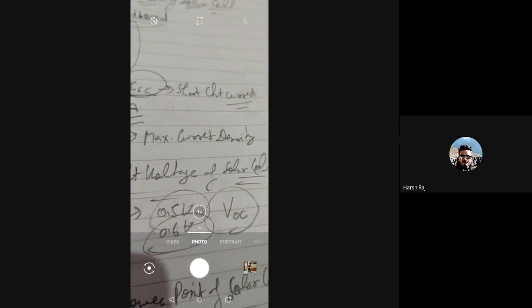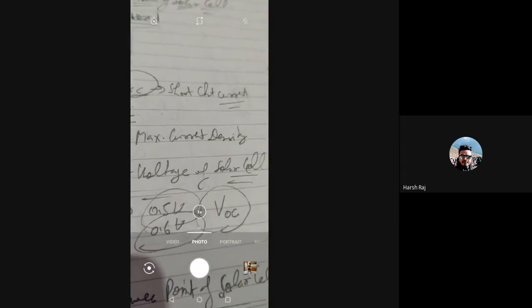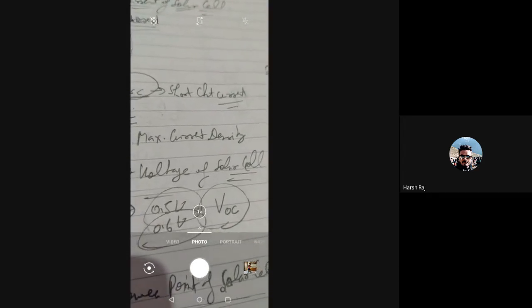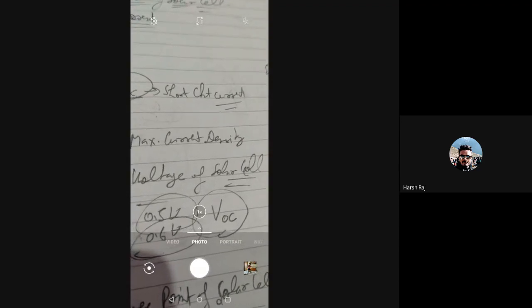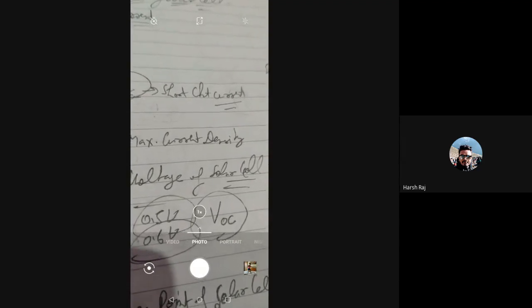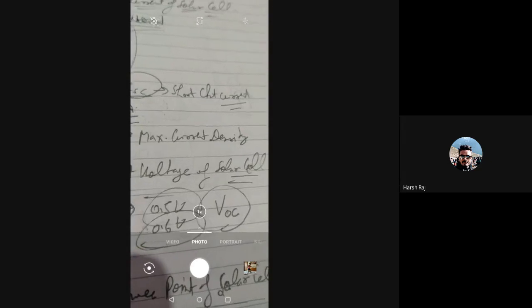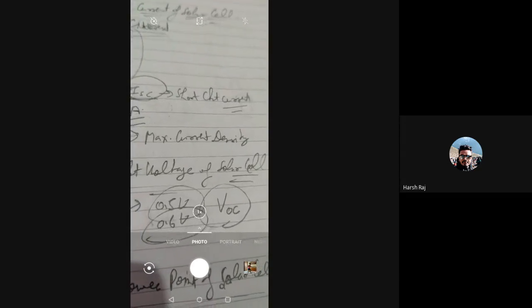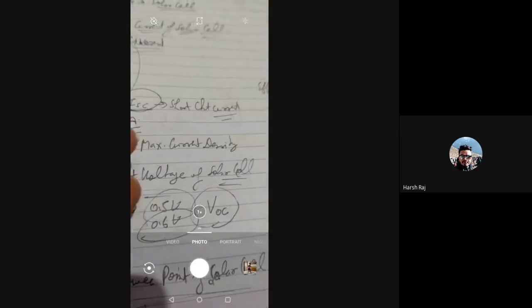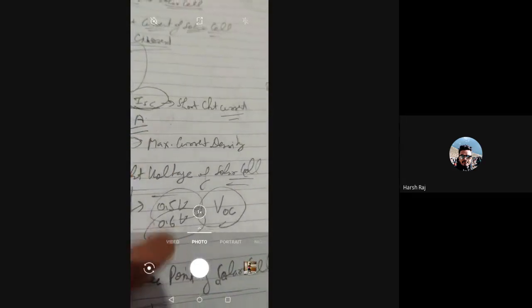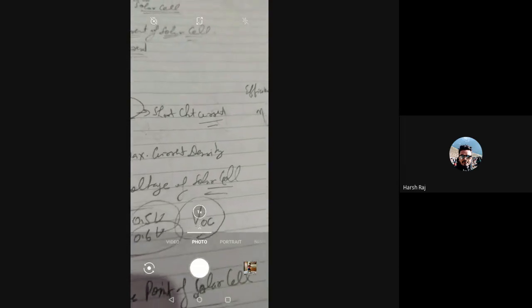Depending upon the PN junction, how the semiconductor contacts are formed, and how the energy gap works, when the photons coming on the cell have energy greater than the energy gap between the valence band and the conduction band, by absorbing that energy the valence electrons get excited and jump to the other bands, and then after losing the energy, they can again form electron hole pairs.